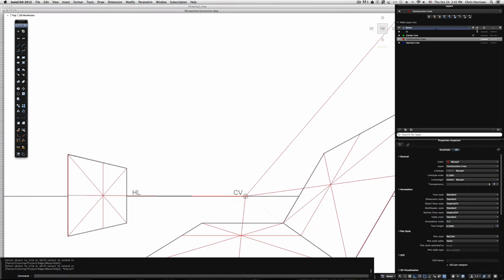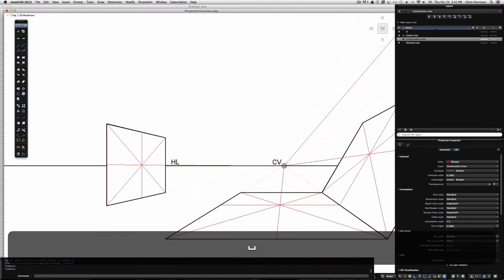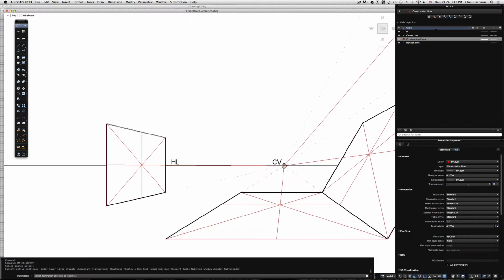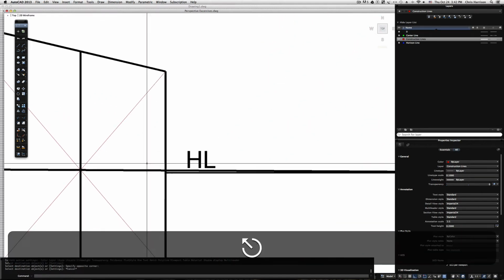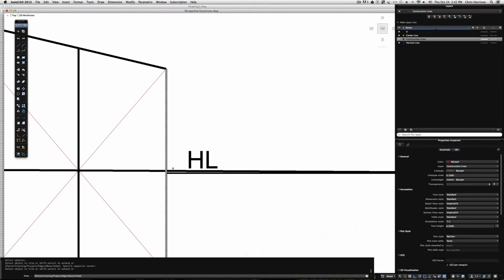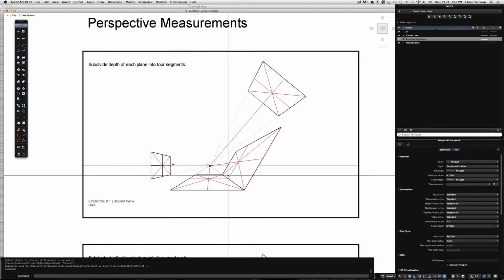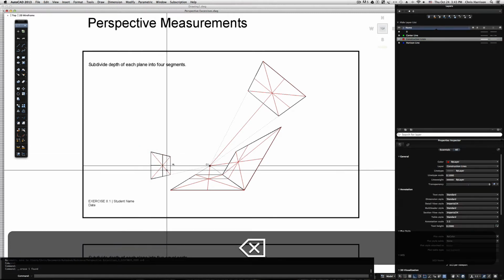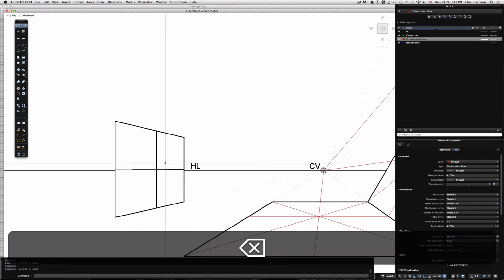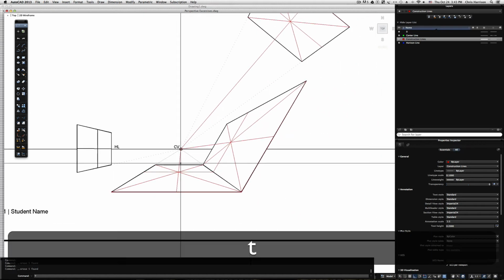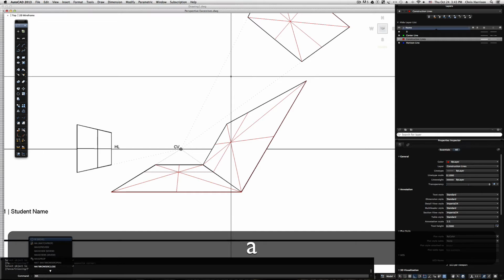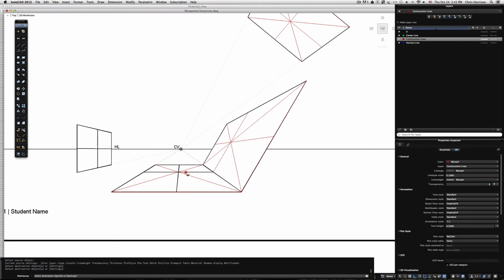What I'm going to do now is unfreeze my layer. If you were doing this by hand, you would just draw your lines in darker to define them. And there it is. Actually, let me trim that. And delete the other lines that I don't need. No longer need the X's. Trim that midpoint, and do that for all of them now. I'm just going to match my properties to that thickness, and get rid of these X's.